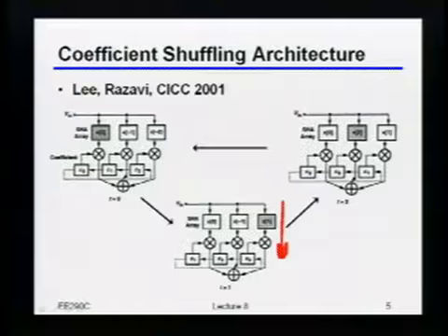Okay, so by the way, just to make sure it's clear, and we'll draw a more detailed example of this in a second. Let's say we said that this is good because it gets rid of long chains of sample and holds. But what are you paying for it? What's the trade-off that you have to make to actually get this to work? More loading on VN. Okay, that's right. You sort of have more loading on VN, and how does that scale with the number of taps? Linearly. Right. So the more taps you have, the more sample and holds you put directly on that VN node, right? Anything else that's more complicated now?